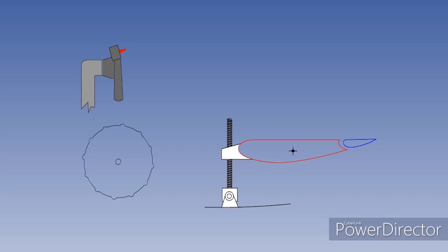Secondly, there are 2 switches on the control wheel in the cockpit. The switches are mounted side by side and are easily moved together by the pilot's thumb when required. The switches are wired in series so that if the contacts of one switch do not break the circuit when the pilot releases the switches, the other switch will break the circuit to stop the trim from running.